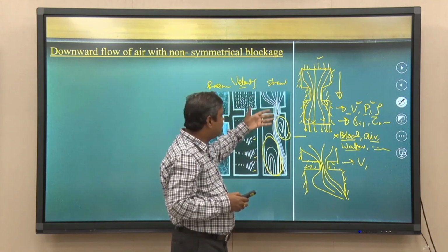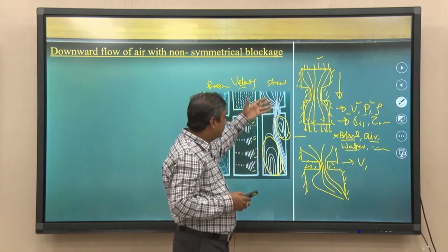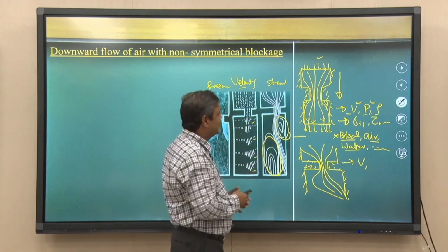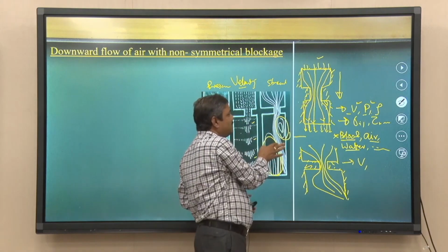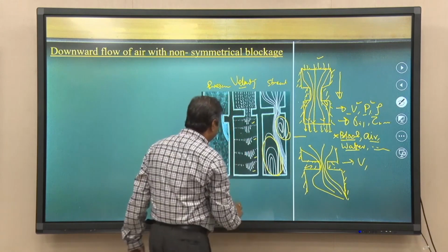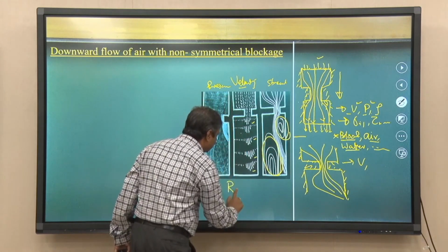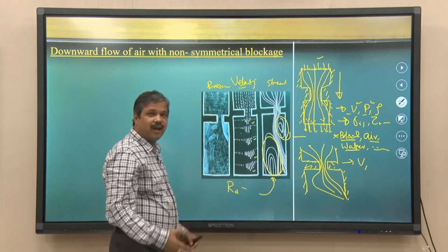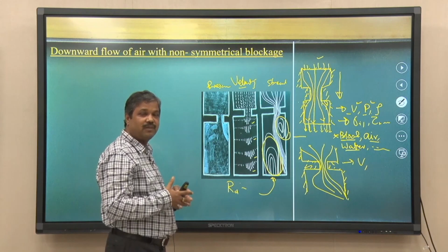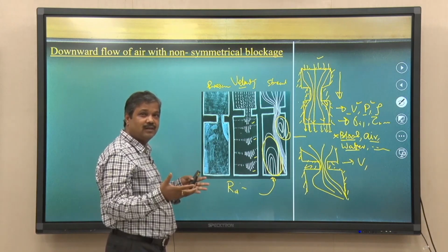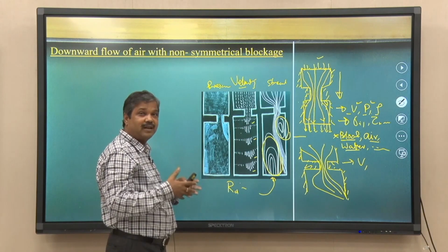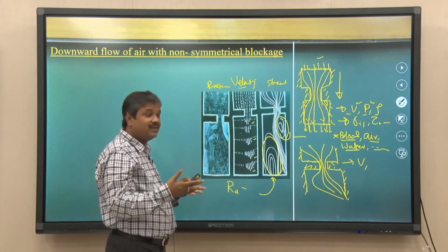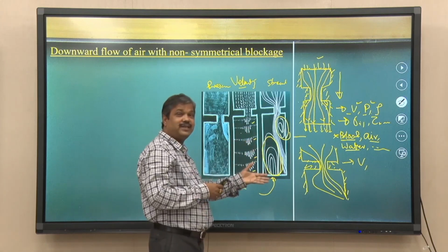Okay. That knowledge has to be developed by solving a series of problems, that what type of flow patterns will be there, as the symmetric case and unsymmetric case, how will you change it. As I change these flow Reynolds numbers, as expected, these patterns will change. If I increase the flow Reynolds numbers, whether you will go for laminar or turbulence, the flow separation zones, all will change. The patterns that you are getting, that will change.